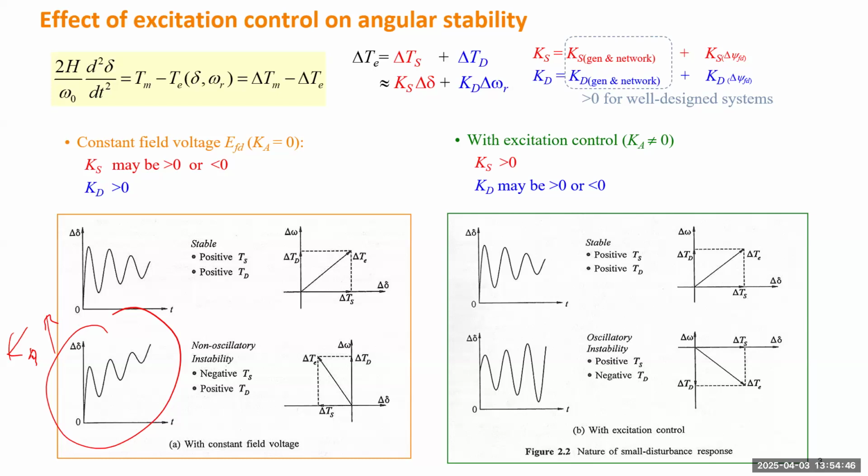But if you see any generator like this one, it means the excitation may be too strong for that generator. But definitely, if you decrease the Ka, that can switch to the first condition, right? So if you jump between those two conditions, the generator always becomes unstable. Either it is flying away from the rest of the system, or it has growing oscillation, which means you do need the PSS. That's a very important trick for you to make a system stable.